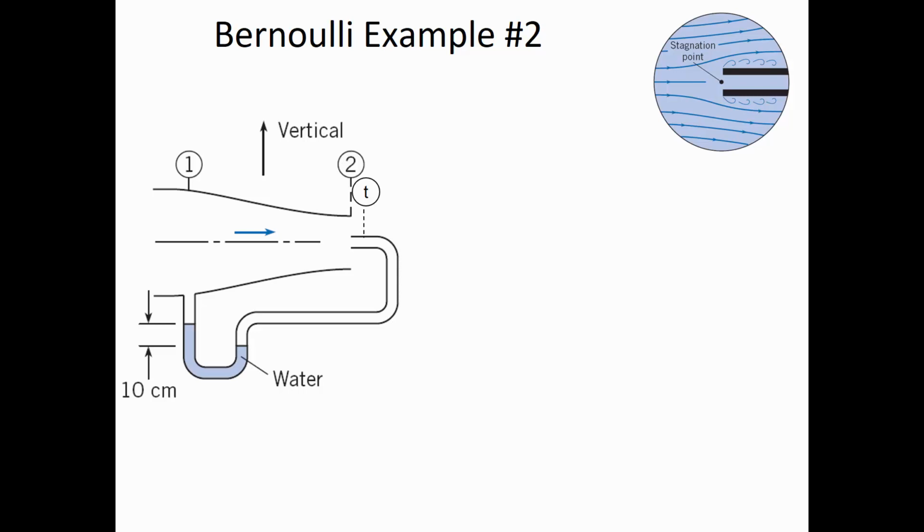But if this gas is running into the tube, then it's going to be measuring the ambient pressure, but then also that wind, intercepting the streamline, there's going to be an additional increase in pressure that is associated with the transfer of the kinetic energy into more pressure. So in this example, we're going to apply Bernoulli's equation at 3 points: location 1, location 2, and then inside the tube. Those will be the 3 spots where we're applying Bernoulli's equation.